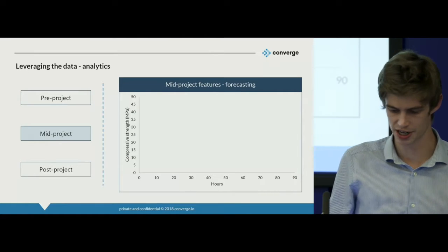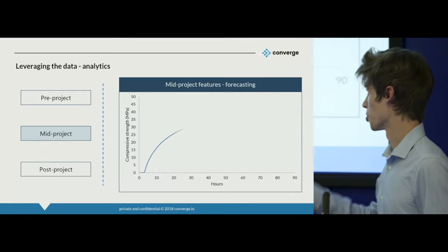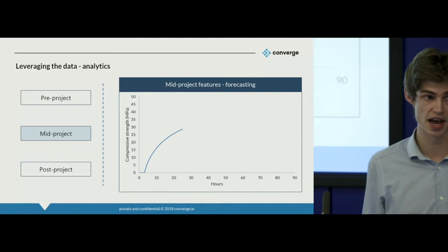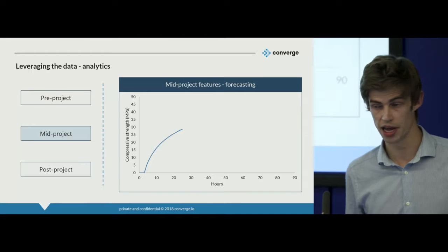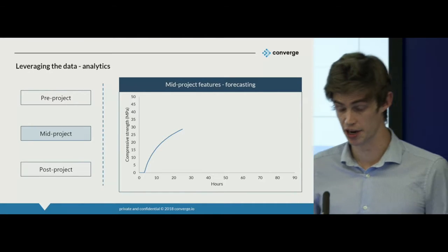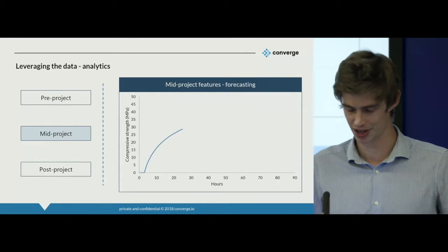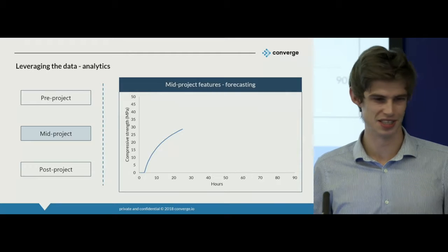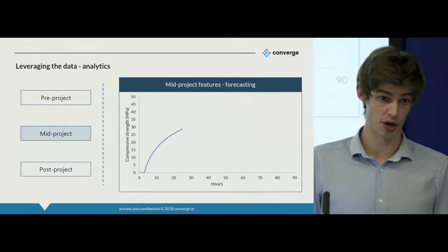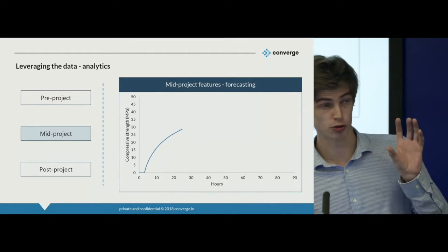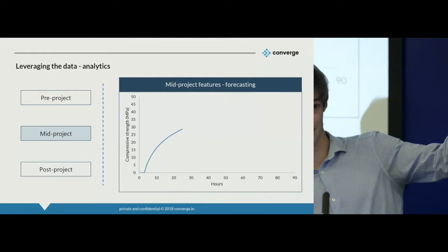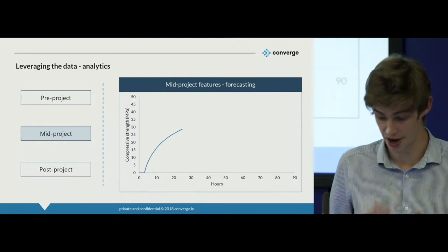In terms of mid-project, today we can tell someone what the strength of their concrete is right now. But what we're building into the platform, using machine learning algorithms and crunching that big data set, is the ability to forecast. So I can know how strong the concrete is on floor 37 of the tower I'm constructing right now.